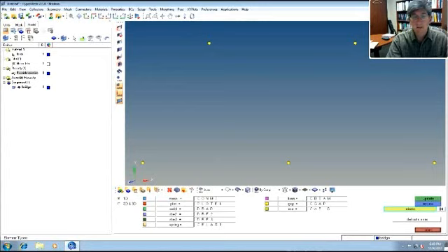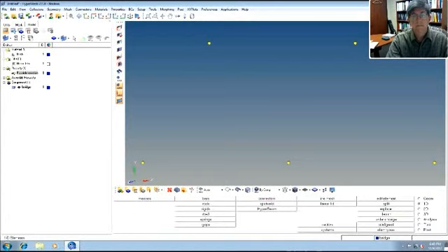So if I click on element types, you can see that by default, a bar element will want to create a beam element. Well, I don't want to do that. I want to use CBAR elements. So I'm going to change that to be bar elements. See? So that works quite nice, actually. And you can do the same for the other ones. So you can change a rod element to actually be a C-rod element if you're so inclined, okay? All right. Okay. So there you go. So now let's create some bar elements.